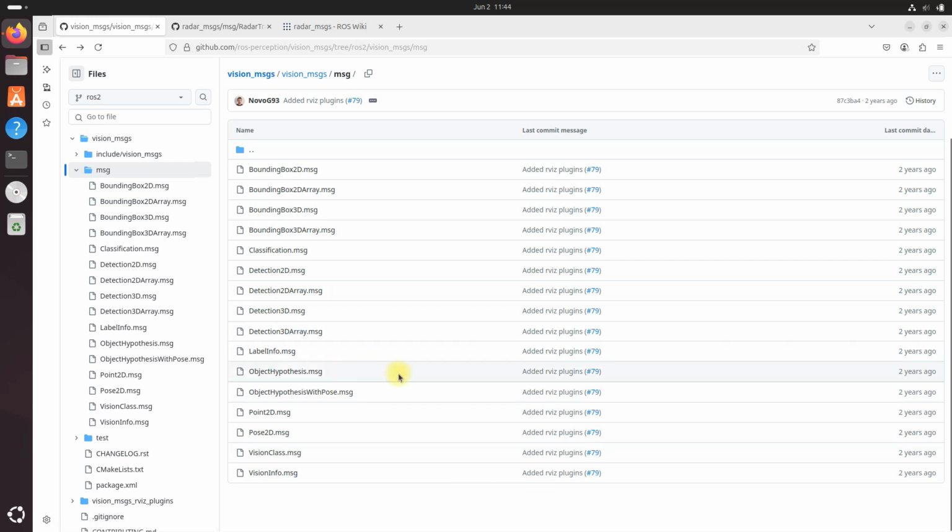As mentioned earlier, most real robots come with special programs called ROS drivers that will allow their sensors to talk using the common language defined in these packages you're seeing on your screen. This makes it easier to use sensors from different manufacturers because general software packages like Nav2 can understand this common language and do their job no matter what specific sensor hardware is being used.